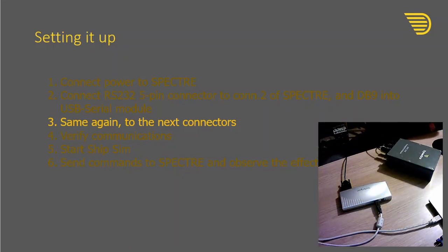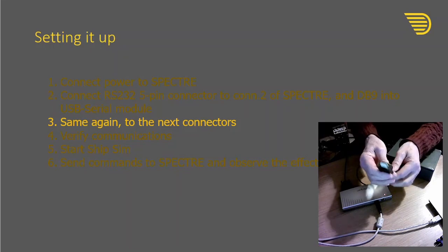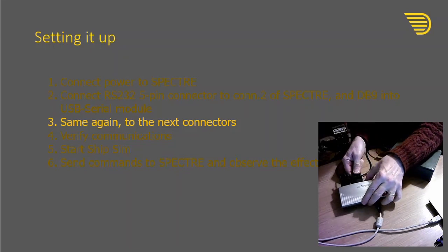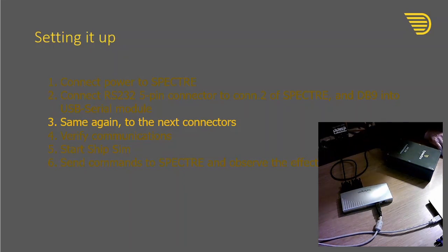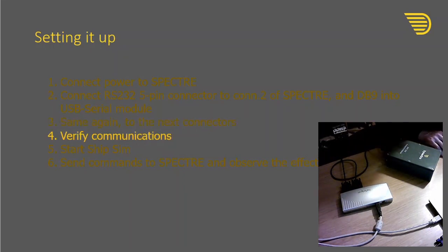Finally, we plug in the DB9 into the next one here. That's good. Making progress. Verify communications. How do we verify communications? The way we're going to do that is by sending some very simple commands into the autopilot and see whether it responds.